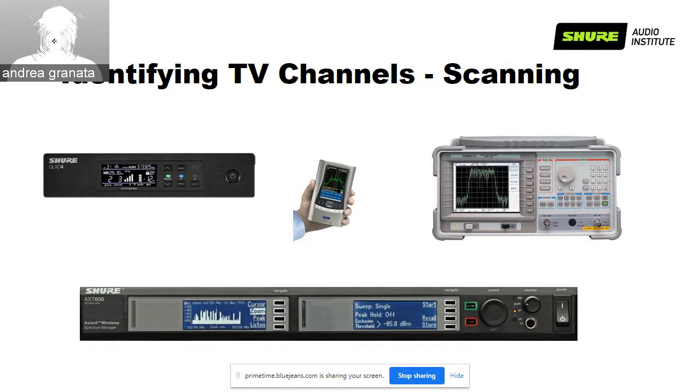What it can do as an analyzer is wideband analysis from 470 to 960 megahertz, so almost everything we may need in terms of frequency coordination for shows, events, and professional wireless in general. And we can capture multiple scans. We can have a single sweep or a continuous sweep. So we can have even up to 24, 48 hours of scanning in order to have a more solid reading of what we need to know about the spectrum.